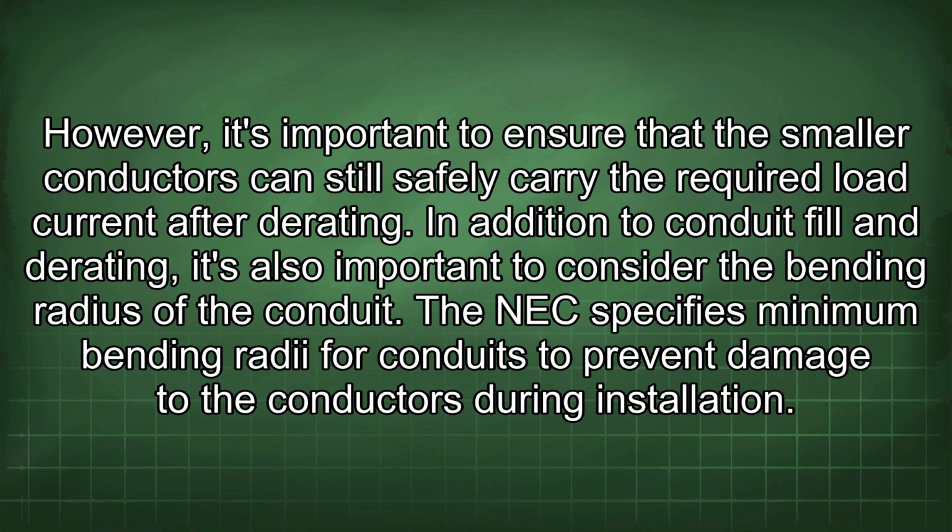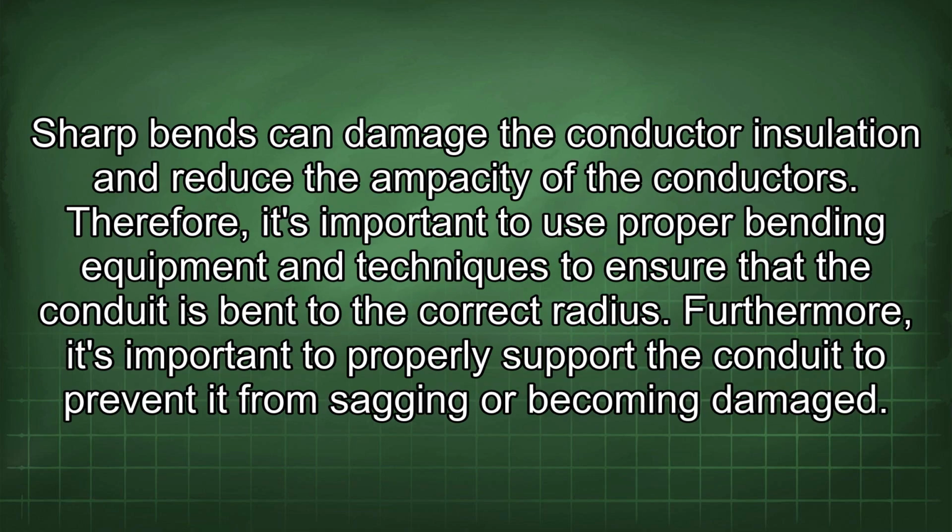In addition to conduit fill and derating, it's also important to consider the bending radius of the conduit. The NEC specifies minimum bending radii for conduits to prevent damage to the conductors during installation. Sharp bends can damage the conductor insulation and reduce the ampacity of the conductors. Therefore, it's important to use proper bending equipment and techniques to ensure that the conduit is bent to the correct radius.